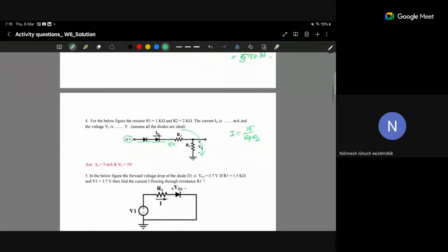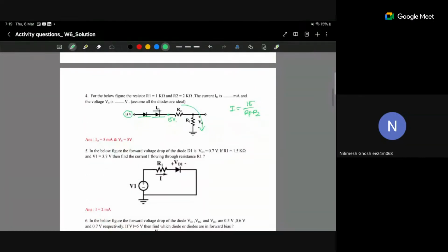Okay, now see, if I say that we have a voltage drop here of 2.5 volt, 2.5 volt, the diode is not an ideal diode, and it is modeled as this diode plus a voltage source of 2.5 volt. Let's suppose the cut-in voltage of this diode is 2.5 volt. Then how can you proceed? What voltage will come to this node? We need 2.5 or 10, greater 10 than 2.5.